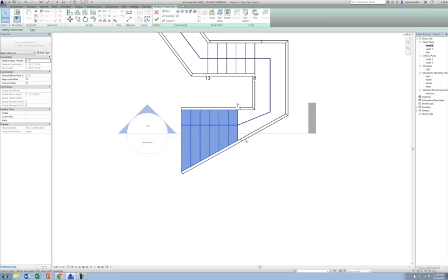And you can see by default it shifts the shape of the stair, keeps all the treads the same, and it even lines up the edge of my landing profile. Although here it looks like it's probably becoming illegal. Again, stairs at a minimum are 44 inches wide inside of your commercial building.